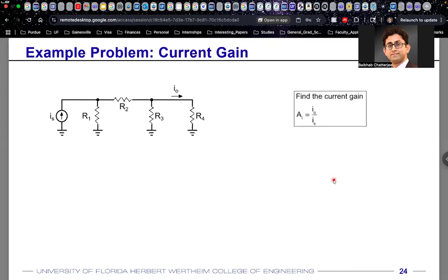That's the transfer function. Again, what does transconductance mean? That the transfer function is a conductance. What transimpedance means is the transfer function is an impedance. And what does transfer function mean? The ratio of your output quantity to input quantity, that is the quantity that you're transferring from your input to output, right? That's the transfer function. And that transfer function could be unitless, it could be a conductance, it could be a resistance, depending on whether you have voltages or currents.